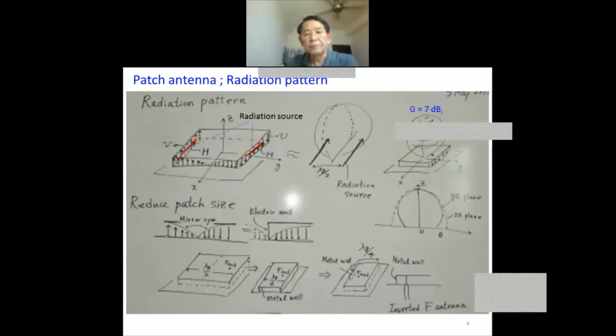So this shape produces antenna gain around 7 dBi. Previously, in the case of the dipole antenna, the gain was 2.15 dBi. So compared to the dipole is this one. With only one radiator, the antenna gain becomes almost 2 dBi. However, when the two radiators exist, the antenna gain is increased, and finally it becomes around 7 dBi.